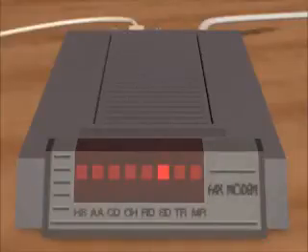Most modems have signal lights which tell you what's happening inside your modem. The MR light means the modem is turned on and ready to go to work. The OH light means the phone line is off hook. The CD light means that the modem has detected a carrier signal. In other words, you've successfully reached another computer. The HS light means your modem is operating at its highest speed.